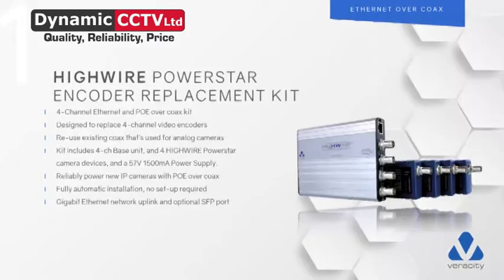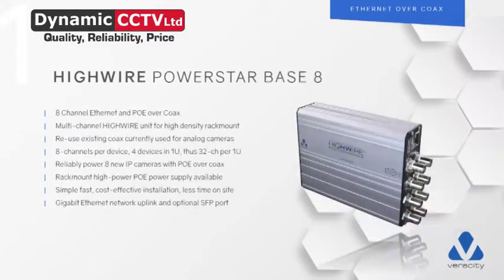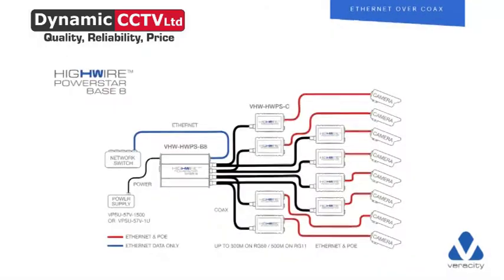So I mentioned then that we could actually use this as an encoder replacement kit. If you've got any old encoders out there, you plug this straight in exactly the same manner as I've just shown you on the previous slide. Base 8. So as I said, we've got an 8-way version of the base 4. I'll flick again through to the diagram so you can see again. So same scenario, DVR, unplug the BNCs, plug it in this, put your power in, plug it into your network, put the Powerstar in your back box, plug your camera in, and away you go. So very easy, very simplistic way of doing things. But again, it's all about time on site, not replacing cables, etc. This is an absolutely first-class product.